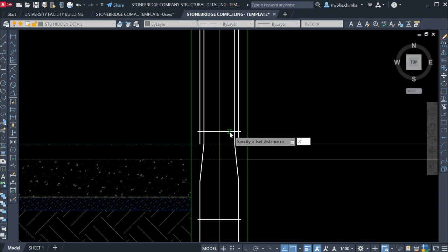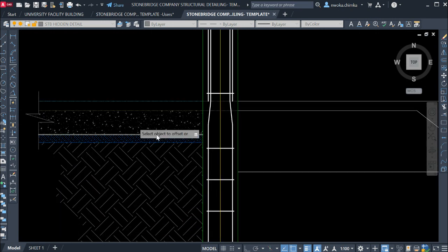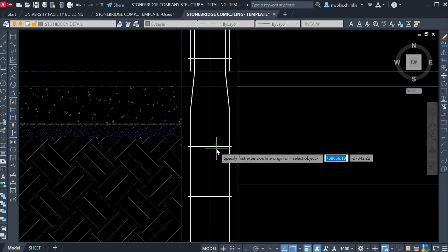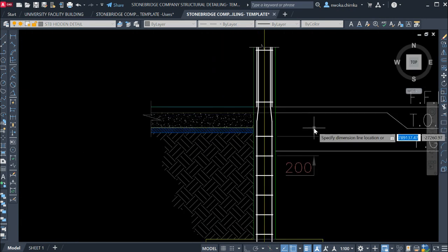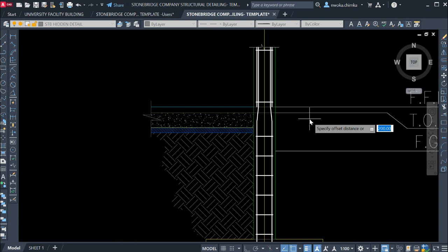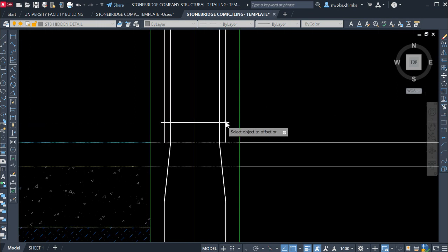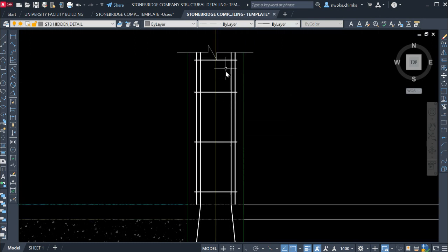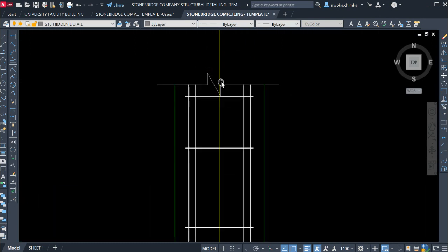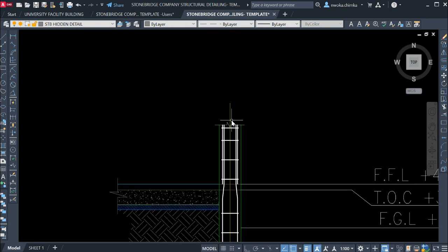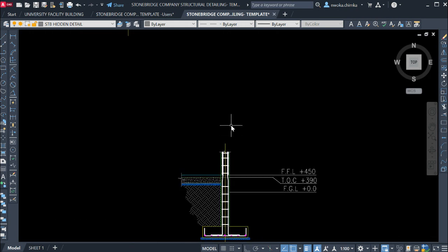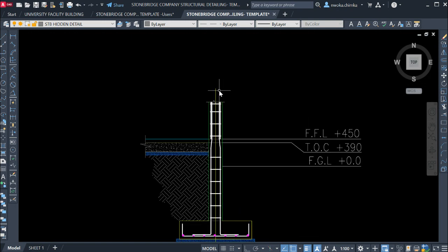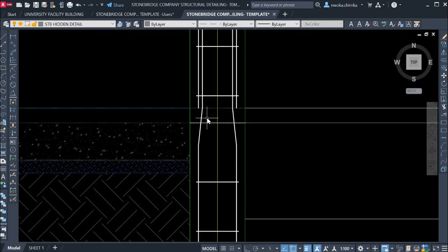Sorry, our link spacing is 200, as you can see it here, 200. If you check it here, you can also see that from here to here is 200. So we have to now offset 200, 200, 200, and begin to offset this and offset this. And then this now shows as our continuity line. So everything happens as a continuity, which I've already shown you before, how to detail a superstructure column, in my videos downward.